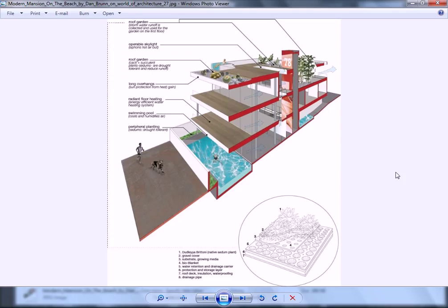Does it need to go all the way through your building? Well, that depends. Like this one goes all the way through to the back side of the building, and that's because it's capturing wind from this side of the building and passing it through out of the back. So it's necessary to have the back side of the building. If your exercise is not using passive cooling and sending it out the back side, then you might only need to show a section of the facade itself.